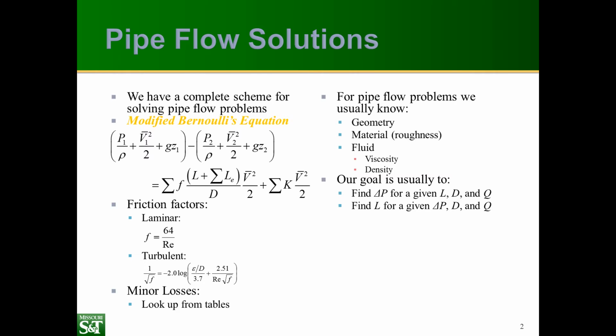These are straightforward, and if we know the Reynolds number, we can obtain the friction factor and we can complete everything else and solve the modified Bernoulli's equation or extended Bernoulli's equation. The second type requires iterative calculations. In this case, the flow rate or the diameter varies, and so the Reynolds number isn't known until we finish solving the problem. So we solve these kinds of problems with a procedure.